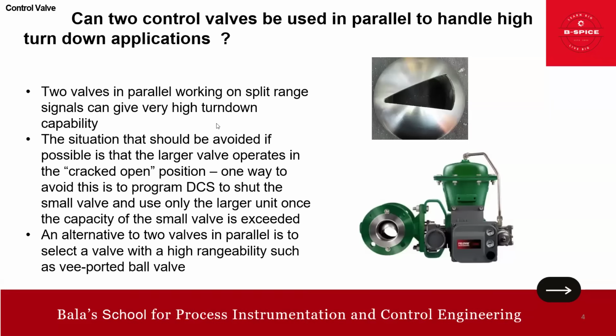So the answer is yes, but there is a situation where the larger valve operates in a cracked open position. So we have to avoid this by programming the DCS in such a way as to shut the small valve and use only the larger unit once the capacity of the small valve is exceeded. The other alternative is to have a V-ported valve. This is just a piece of information I want to give you.